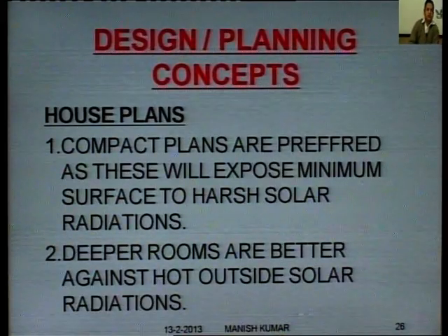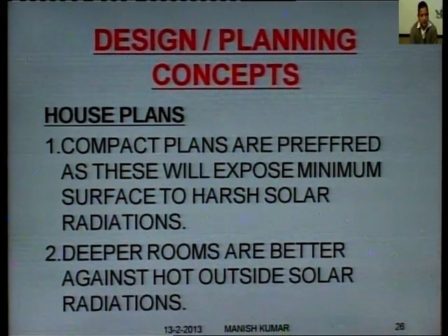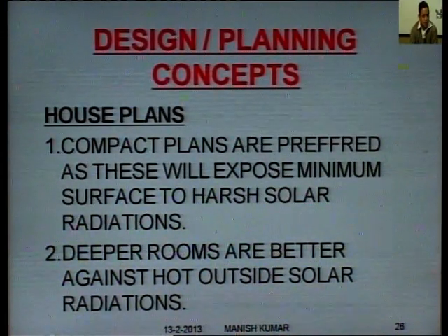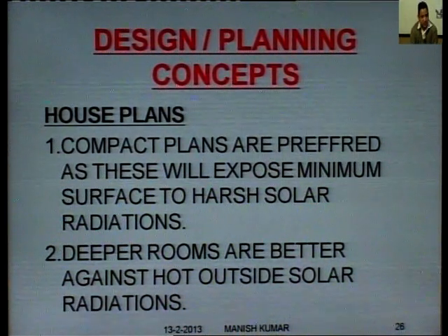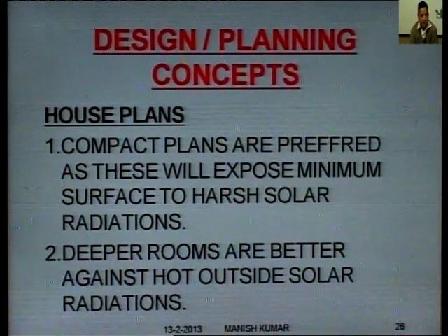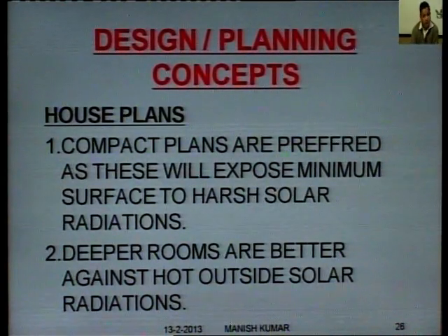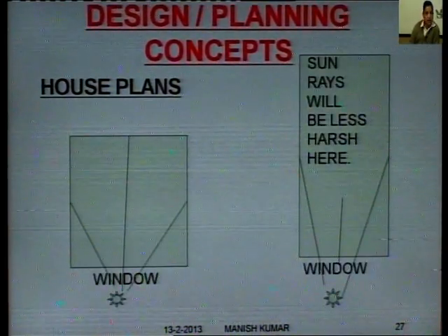After orientation, we have house plans. Compact plans are preferred as they expose minimum surface to harsh solar radiation. Yes, our planning should be compact to avoid solar radiation. Second, deeper rooms are better against hot outside solar radiation. This point will be clear from this slide.